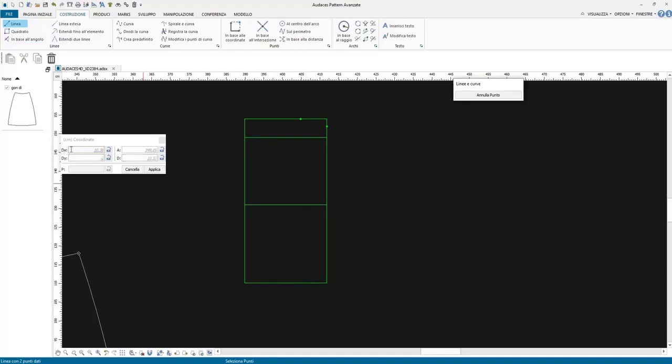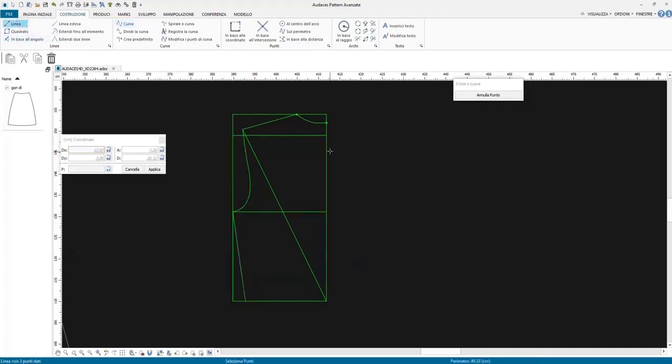To create the length of the back, use the Line tool and insert the measure in the distance field. Click in the angle and reach the border of the circle. Now join the points of the shoulder and the neckline. Create the armhole using the Curve tool, where we click the software adds a curve point to change the shape of the line. Then finish the base making a line. That is the back graphic.